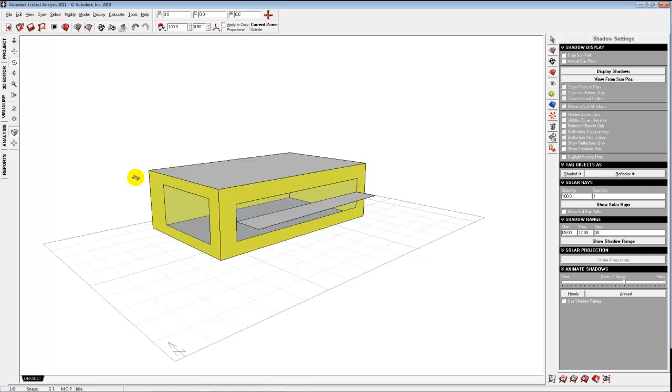So again, I just want to show you this to show you how you used to get started modeling things in Ecotect, because as you bring your models in, especially as you start thinking about making changes from your precedent house to some of the interventions you'll want, a lot of times it'll be easier to just make small changes right in Ecotect as opposed to going back to Rhino and making the changes and doing the re-import. Especially if we've had to do a lot of cleanup on your Rhino model to make it a nice analysis model, it may be easier to make the changes right in here. Things like adding windows, subtracting windows, adding light shelves, things like that.